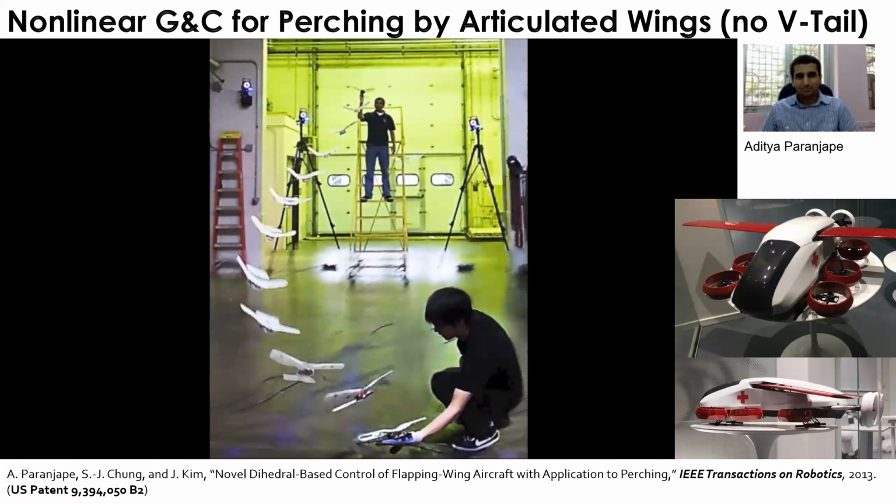I'm going to talk about a couple of extensions of this sequential convex programming used for solving the real-time nonlinear optimal control problem, which can be used for a motion planner. One example is collision avoidance. We do a hyperplanar approximation, which can be very conservative in an obstacle-rich environment, although it worked very well in open space. So what you can do is a spherical expansion. You can use a graph-based approach to generate a path optimizing a certain cost function, maybe without using the dynamics.